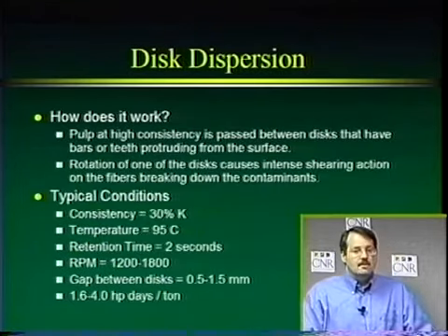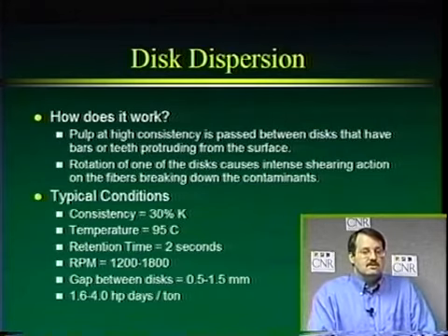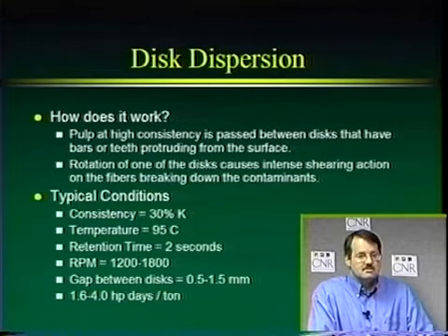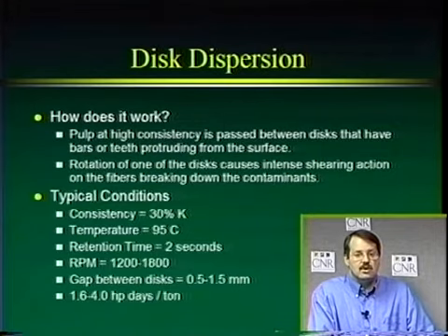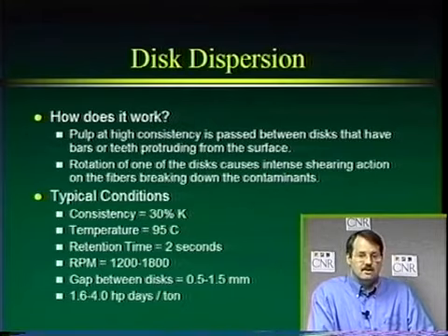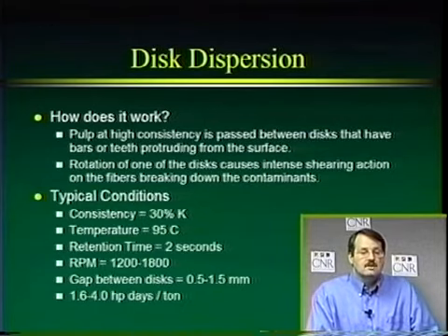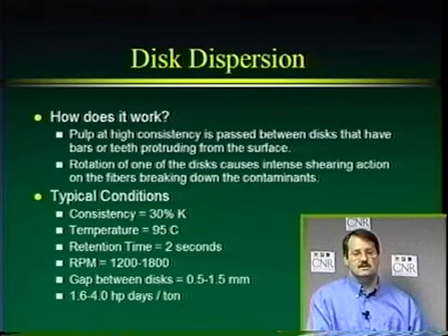Okay, there are two methods to do this dispersion, and one of them is disc dispersion. We'll talk about that first. The other one is what's called kneading. The two processes work a little differently. Same concept, but the mechanical actions are applied in a different manner. We'll contrast these two. So first, let's talk about disc dispersion.